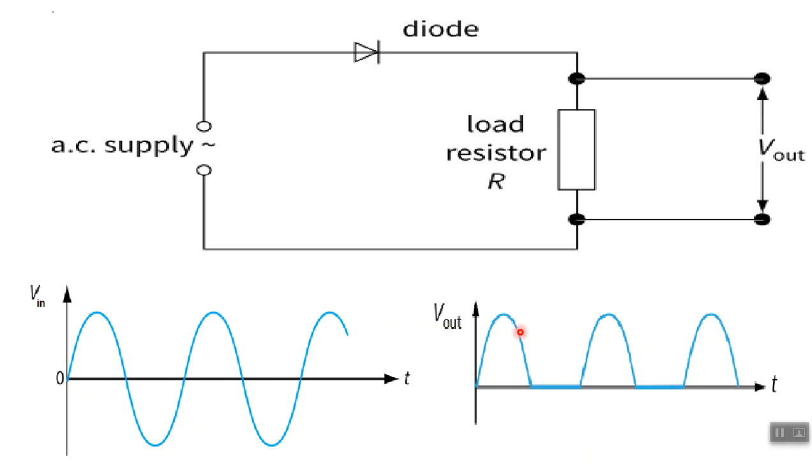There are other ways to even smooth this out much more without having the off parts, but this is simply how a diode alone can turn AC into DC. Although this is not ideal for something like a cell phone, we need a few extra components to make it smooth, because we don't want to have something switch on and off the whole time, if we could help it.